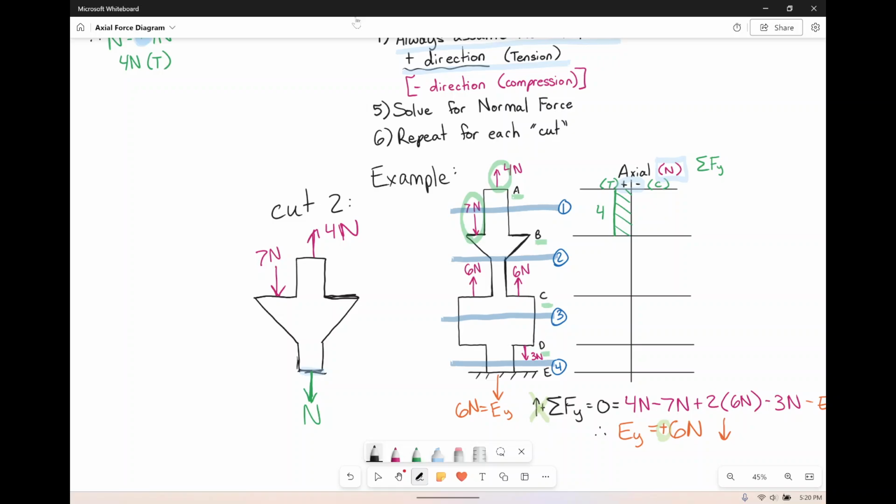So let's do the same thing again. Let us sum some forces in the y direction. Set it equal to 0. Again, for this equation, I'm going to assume up is positive. Got to state it. Got to pick one direction to be positive. So what do we got? We have 4 newtons going up. We got 7 going down. And N's also going down, so he's also negative. So you do the math, and what do you get? You get that N is equal to 3 newtons, but we get him to be minus 3.